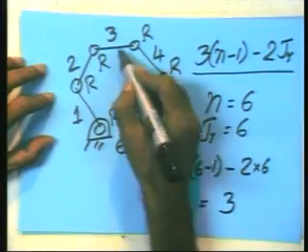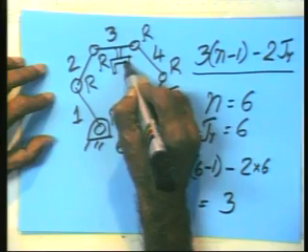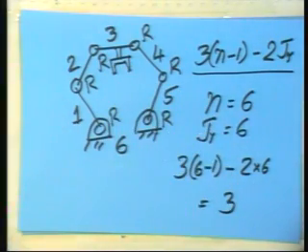So this can orient an object. Supposing I put my end effector here. Not only can you position it where you want, but again remember the workspace here is considerably smaller than what you get in the serial chain. It would be instructive if you could work out the workspace of the 5R planar chain. You just try to work it out by drawing the workspace.